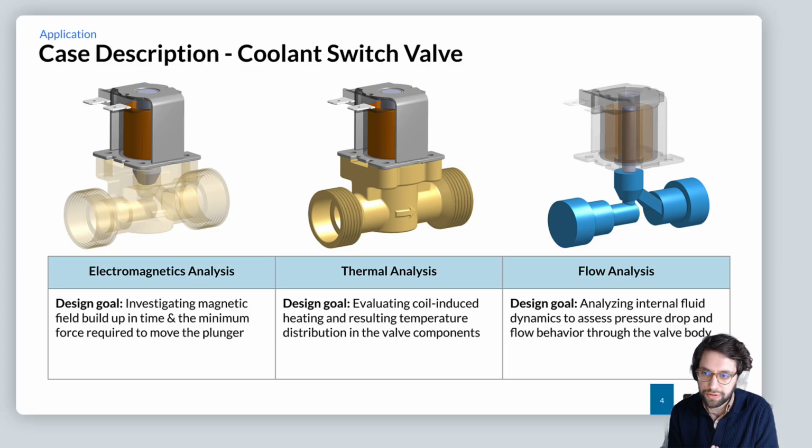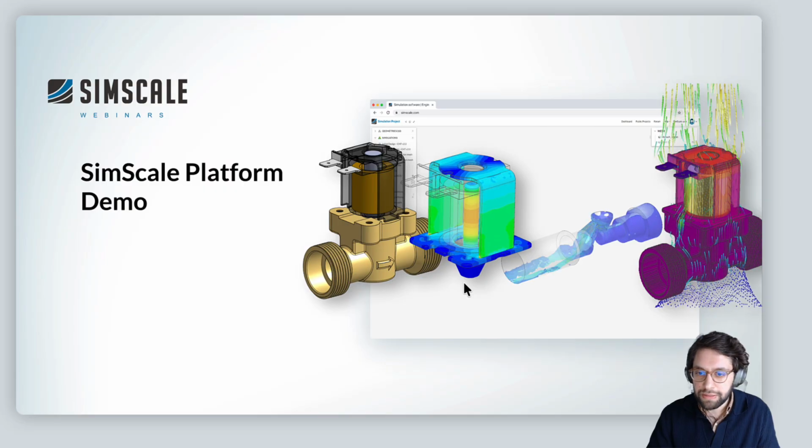And of course, after all of that, we could run lots of different simulations of different valve openings, analyzing different flow rates and just understanding how does the valve perform from two points of view. As one of them is the pressure drop in the system, but also is the fluid flow structure optimal. And what I mean by optimal, like do we have large recirculation areas, etc., etc. Right?